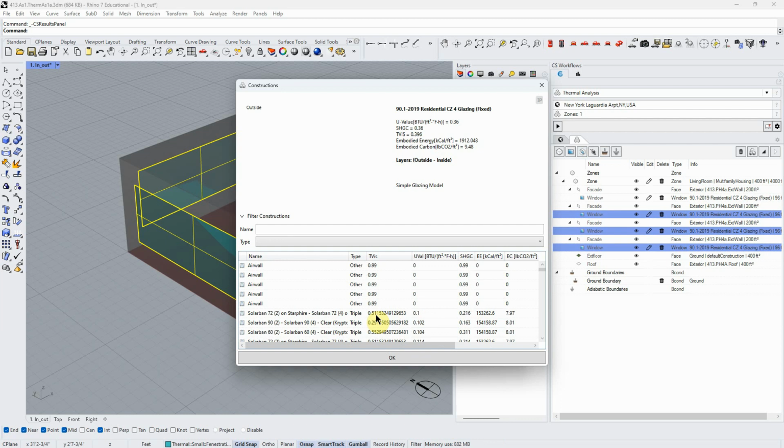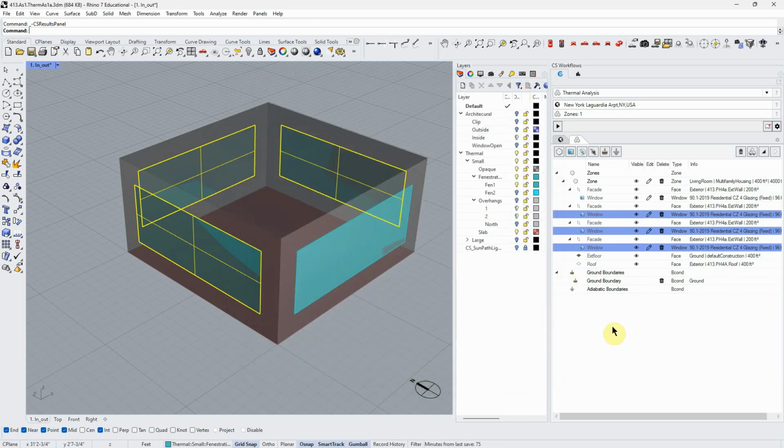So this is again like what we were talking about at the beginning of this video. I'm only letting through about 22% of what will become heat inside the building, but I'm letting through 51% of the potential visible light. And we're doing that through scientific design of glazing that we've developed over years of practice. So okay, anyway, let's see what this does to our model. I'm going to run it. And again, all I did was change those. I could have done that in 10 seconds if I wasn't talking to you about it.